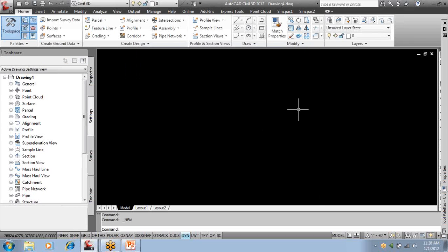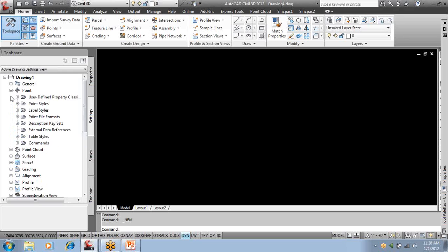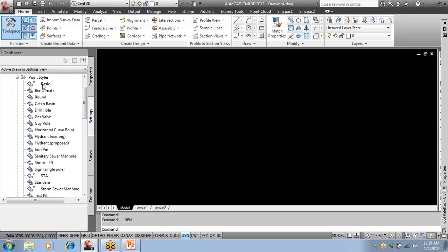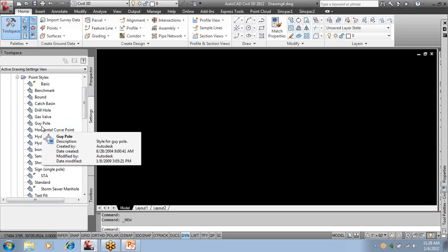In part 2, what we're going to do is use the National CAD Standard template, and I'm going to show you how to use all the styles that come with it. Not just the layers and the line types and the blocks, but under settings, every object that you work with, you have styles. So the National CAD Standards provide all these styles for you. Point styles are going to be every single block.